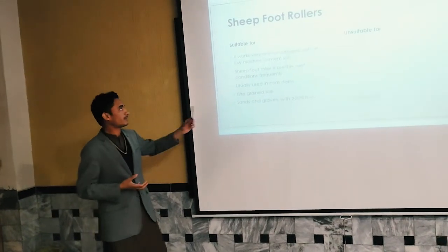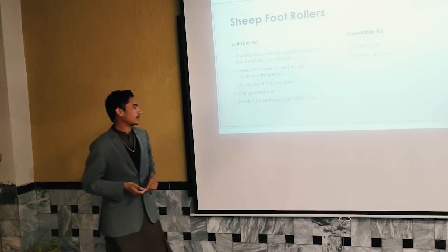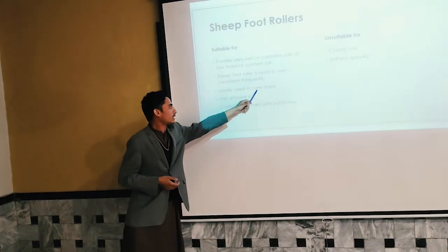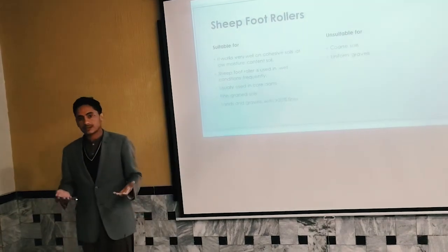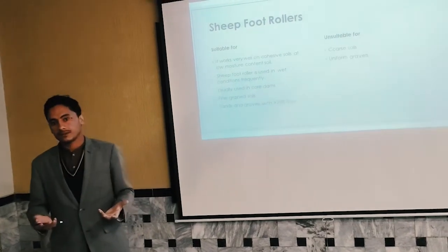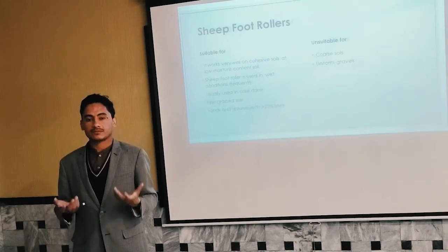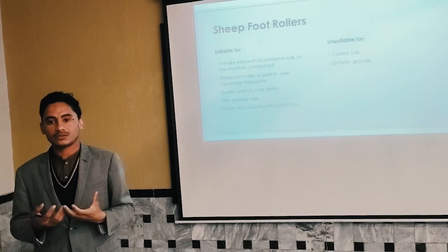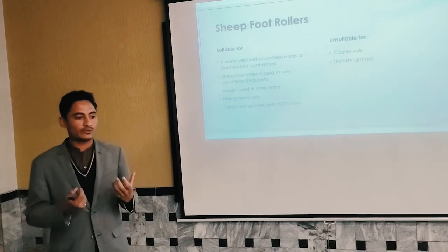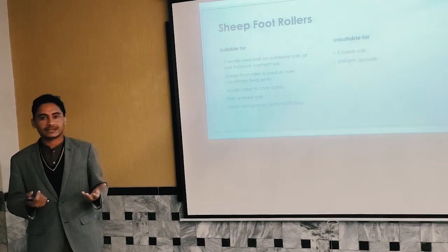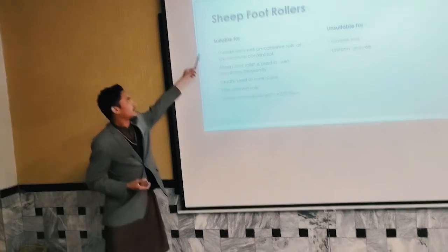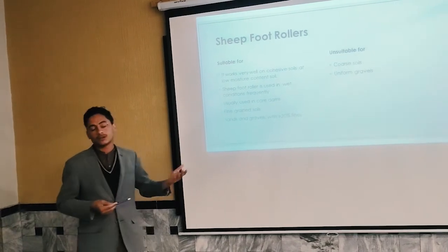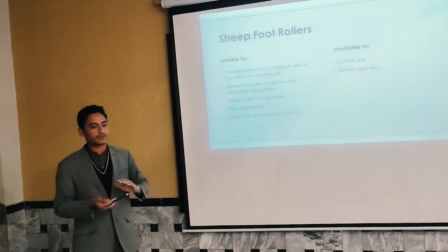So therefore, we prefer the sheep foot roller when we want to construct a dam or other structure where we need less moisture content. If we use the pneumatic roller, there will be no proper compaction.